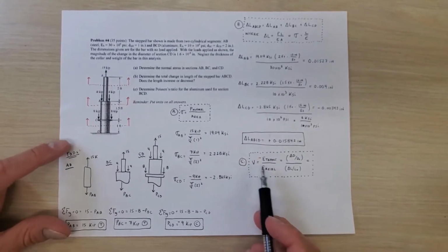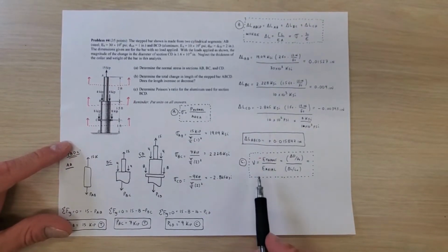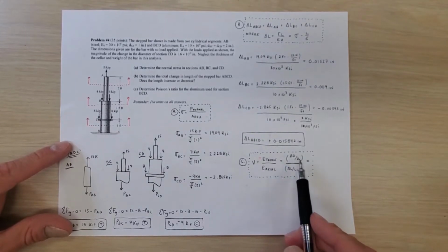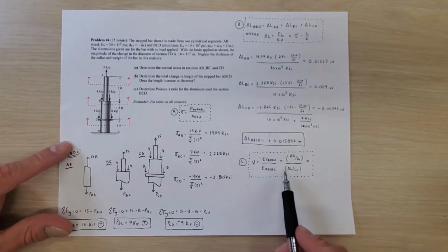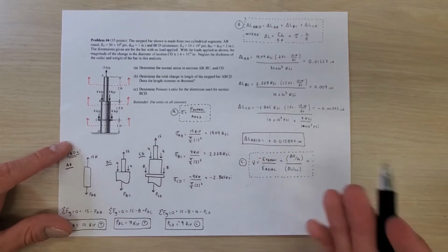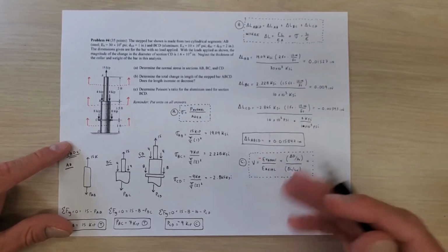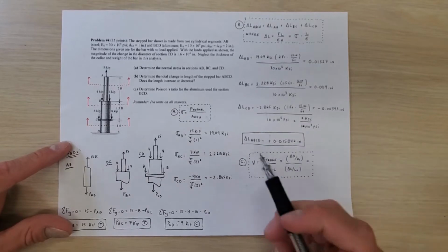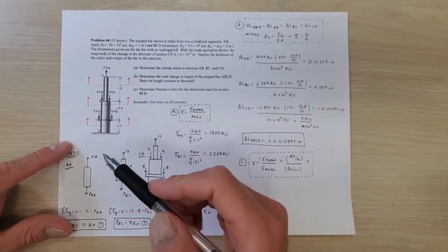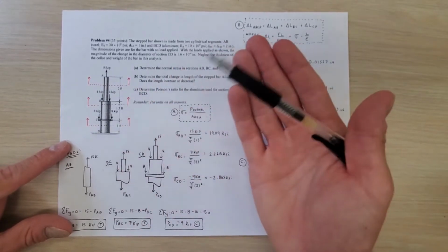So for Poisson's ratio in part C, we know that it is equal to the negative transverse strain over the axial strain. We know that transverse strain is change in diameter over initial diameter, whereas axial strain is the change in length over the initial length. We can see that all of this is going to be unitless, so we just have to make sure that all our units are going to match, which we'll use inches. And we can plug in everything we know for section CD, which is the part that we're trying to determine Poisson's ratio for. And CD is a part of BC, and because this is all aluminum, it's the same thing.